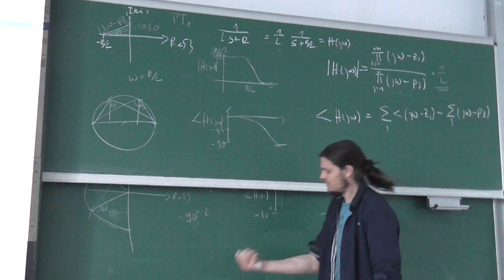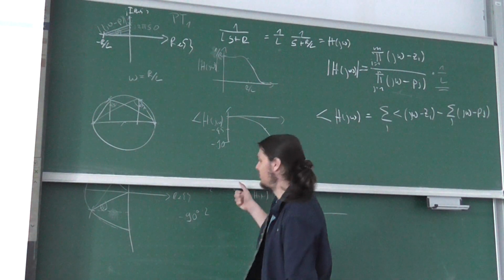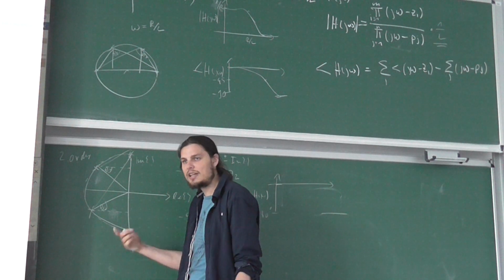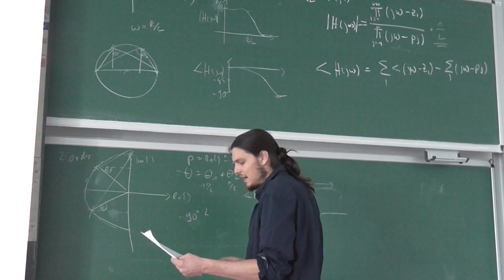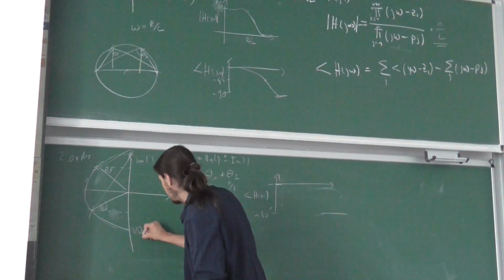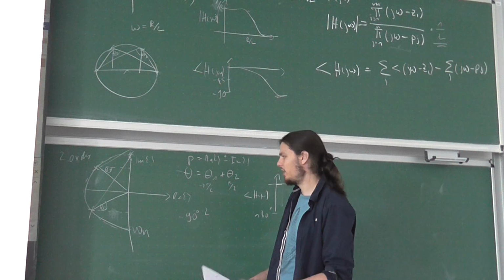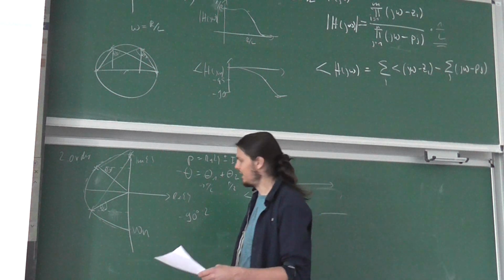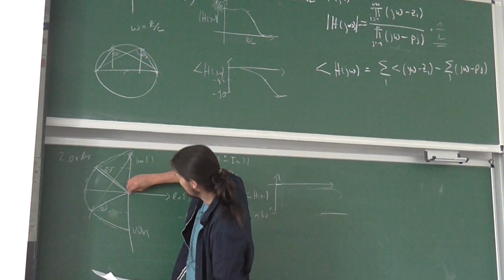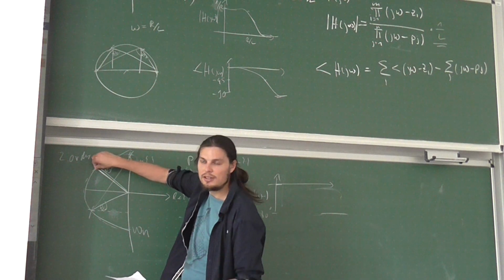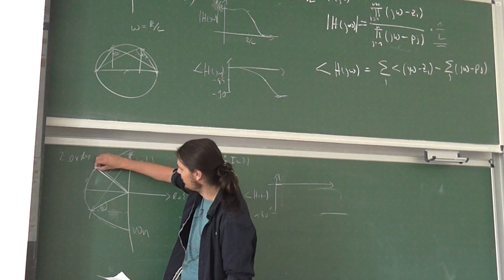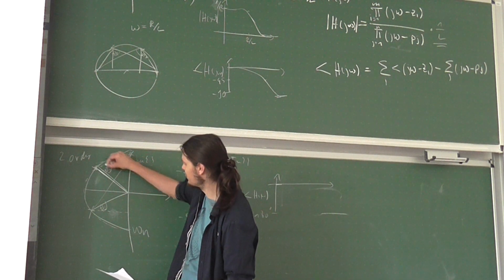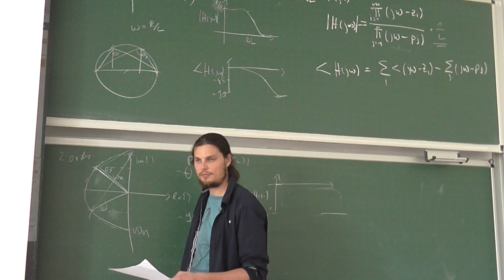So we know this happens exactly at this circle point. We can calculate the circle, and it has a name. It's what we call the natural frequency. Okay? So this we call omega n, very often referred to. And this is actually also the length of this, right? So it's basically the magnitude of each pole to the origin. Right? This is our natural frequency.